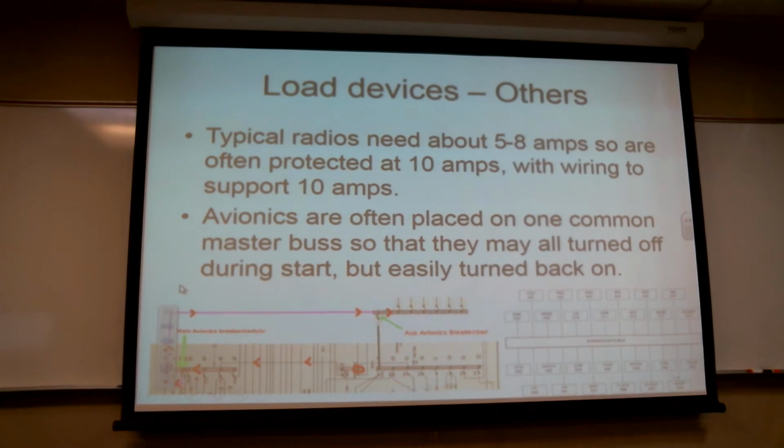The other side of that, and where the on can be problematic, is we don't really know what the power source can put out relative to the initial inrush current. So if I've got a fairly small cold cranking amp battery, let's say, and I hit it with the starter, what's going to happen to the voltage? It can't put out that much because the cold cranking amp is pretty low.